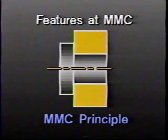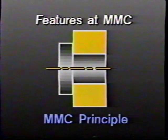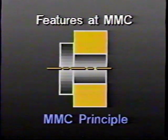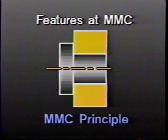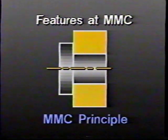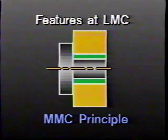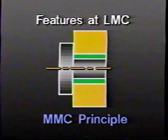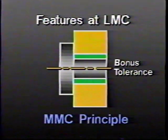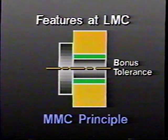This maximum material condition principle recognizes the fact that when mating parts are at their maximum material condition, or worst case condition, the tolerance specified by the design engineer must be held to ensure proper assembly. However, as mating features approach their least material condition, they fit together more easily. So additional tolerance can be allowed without adversely affecting the part's assembly or functional requirements.